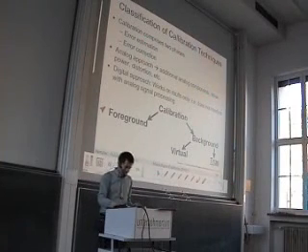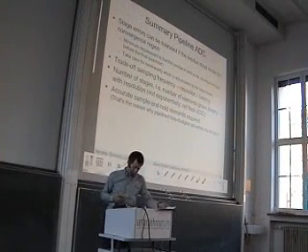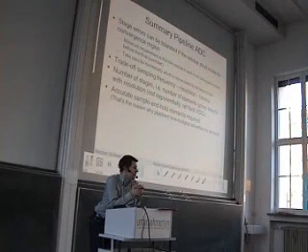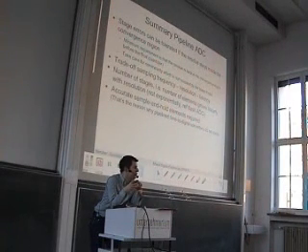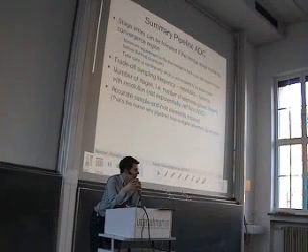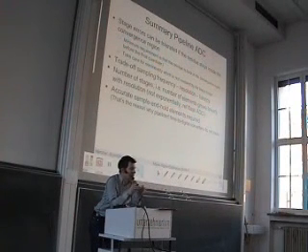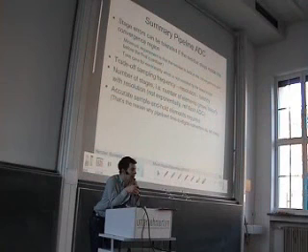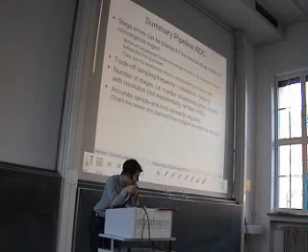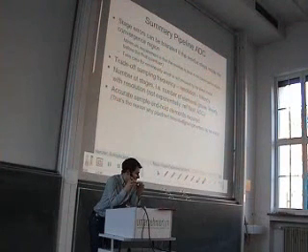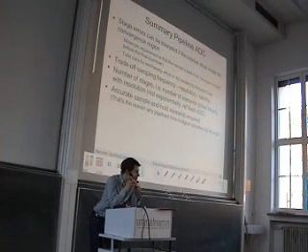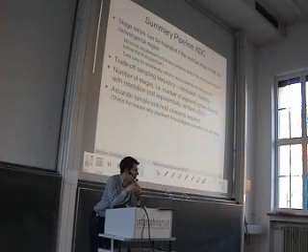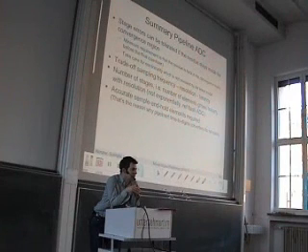Okay. Let me conclude the pipeline chapter. We saw that stage errors can be tolerated as long as the residue stays in this convergence box. Or at least it should be scaled back into this convergence box before we reach the final ADC. We have talked about words like latency and throughput, and I hope you got the difference here and saw the advantage of the pipeline ADC.